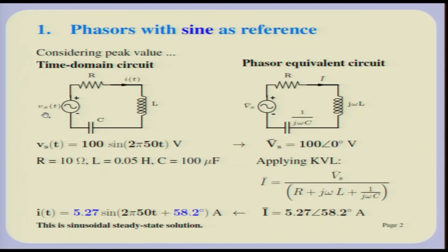Only what we can capture is the phase and magnitude information. So, when I for example represent Vs is equal to 100 sin omega t, this is a 50 hertz waveform, then one of the ways of referring to this sinusoid, once it is implicit that this is containing that frequency, is Vs is equal to 100 angle 0.